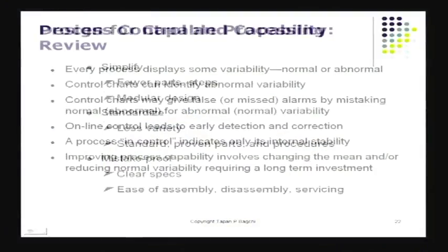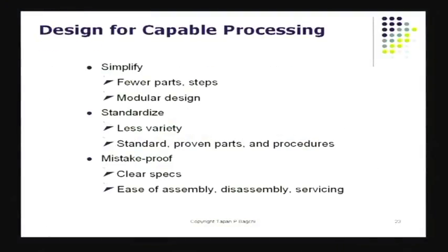Once these variations have been located, you've got not much to worry about. All you have to do is adjust the settings of those factors, the factors that turn out to be the culprits. You adjust them in the right direction, the process will restore, the average X double bar will come back to target, and also sigma will reduce. The overall variance of the process will reduce. This is something that we need to do. This is a very interesting area.